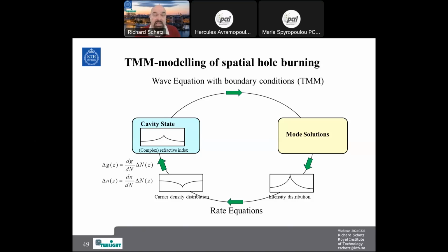In LaserMatrix, in the static model, I assume it will be single mode, and then I get the carrier density distribution. From that carrier density distribution, I calculate all the side modes. However, dynamically, I take into account how all side modes are added together and affect the carrier density together. So the dynamical model is a fully multi-mode model.